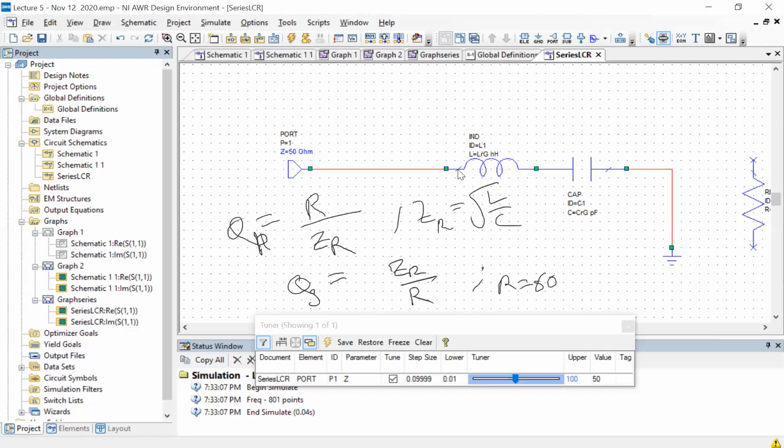And again, the reason that it works at lower frequencies is what we discussed in one of the first lectures about the wavelength. At such low frequencies of kilohertz versus gigahertz, you're talking about a 10 to the 6 difference in the wavelength. So the wavelength at kilohertz frequencies is huge. So everything looks like a lumped element. You don't have to worry about the fact that your inductor is now the size of a lunchbox. It's perfectly fine. The phase is uniform across the entire inductor. There's no problem in getting it to work. It will have some resistance, fine, but that resistance will also be small compared to the L in the kind of Cs you can get.